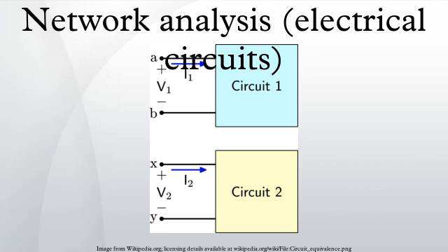The voltage across any impedance equals current times impedance. Current division of parallel components: consider n impedances that are connected in parallel. The current through any impedance is given by the total current times the ratio of the equivalent impedance to that impedance. Special case: current division of two parallel components.